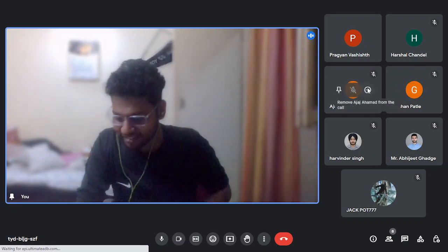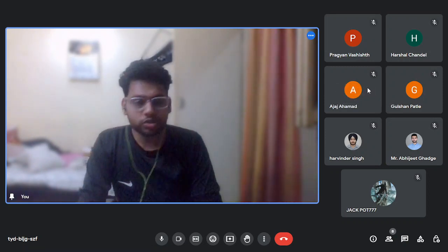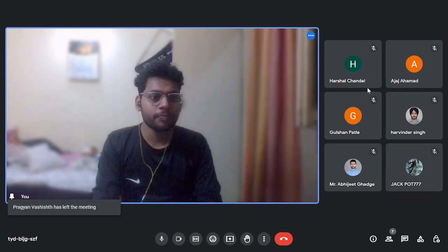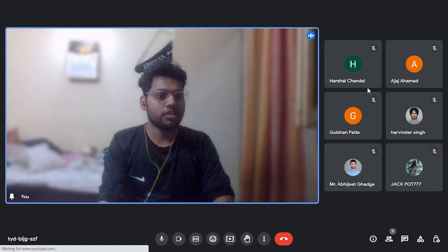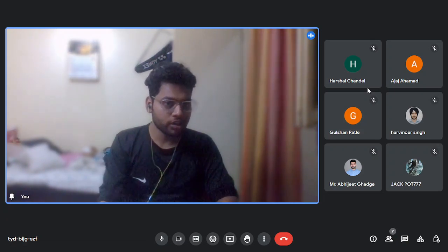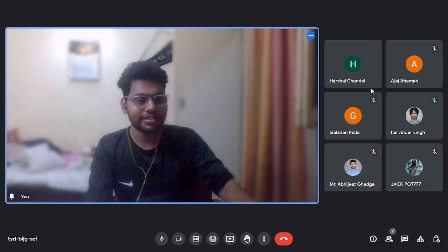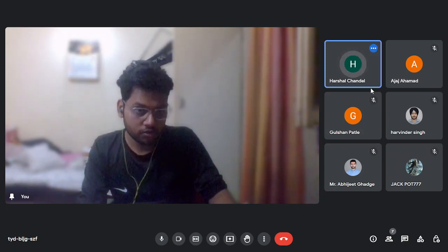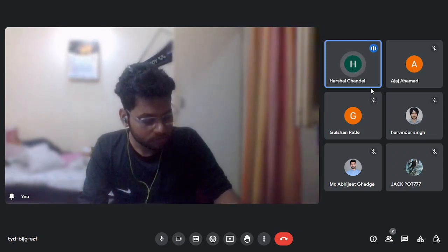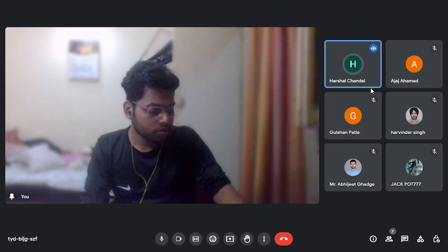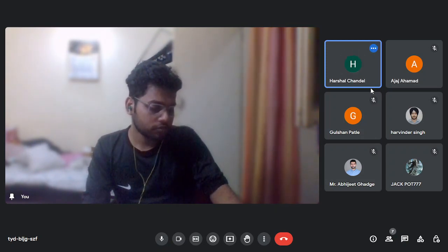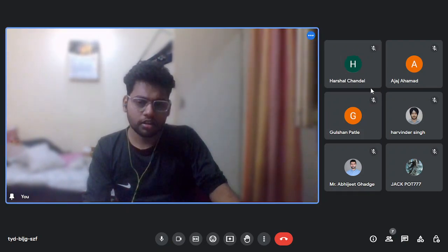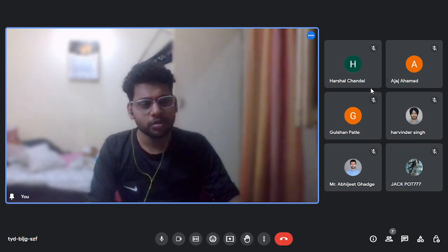Okay, Pragyan, take care. So guys, my next question is, what are boiler accessories? Who is going to answer? Harshal is there. I am not asking about boiler mountings. I am asking about boiler accessories. Basically, the boiler accessories are there to increase the efficiency of the boiler. If I name the accessories, we have the air preheater, economizer, then we have heat pump, right? So all these are accessories. Air preheater, economizer, I agree. Heat pump? Are you sure?